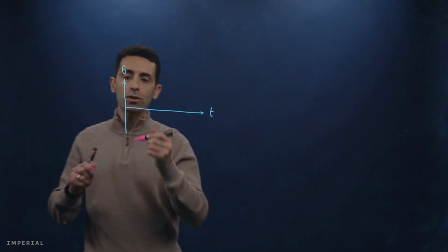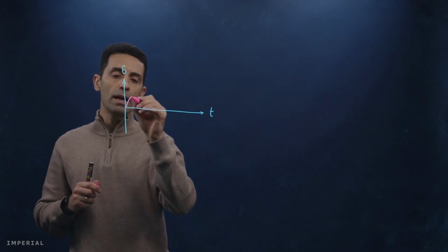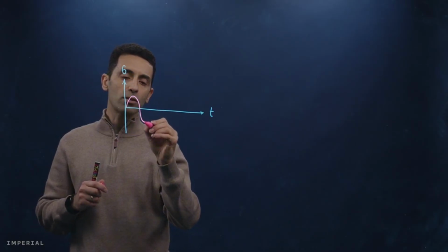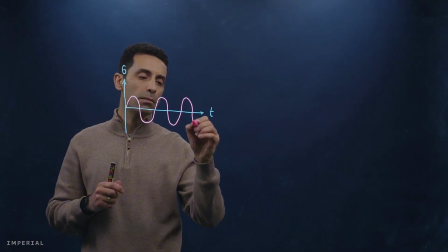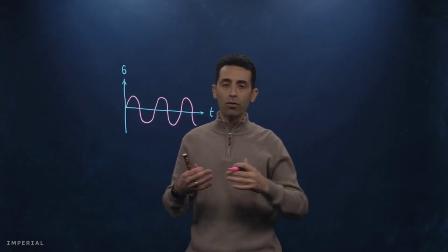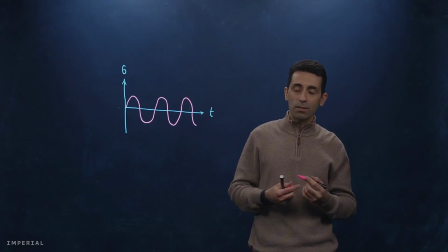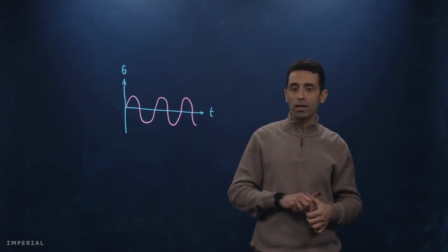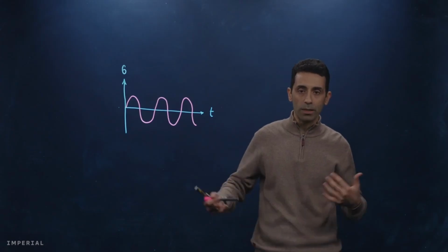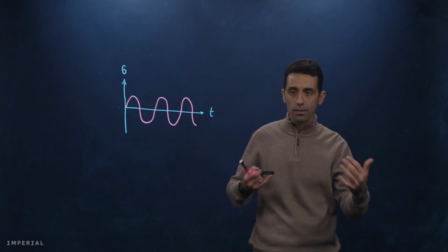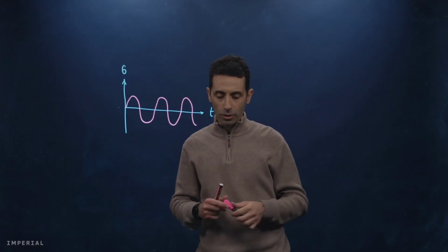So the load was going to a maximum and going back, reversing again, going to a maximum, to a minimum, maximum, minimum, and then this can continue for, as I mentioned, thousands or hundreds of thousands of cycles. Imagine a bicycle crankshaft, how many times you pedal. That is when you're applying this cyclic loading on the structure.